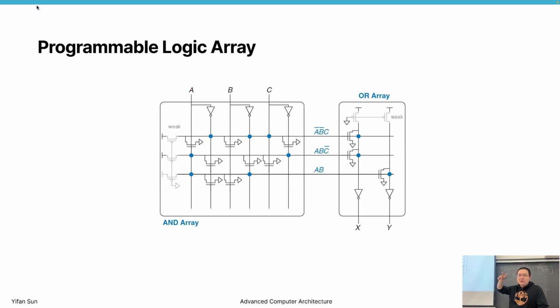Otherwise, there are too many possible inputs. Like multiplying two floating-point numbers, 32-bit input, 32-bit output, there are too many combinations, right? It's 2 to the power of 64. That's too many combinations. It cannot be achieved with lookup tables. So FPGAs today are equipped with multipliers.